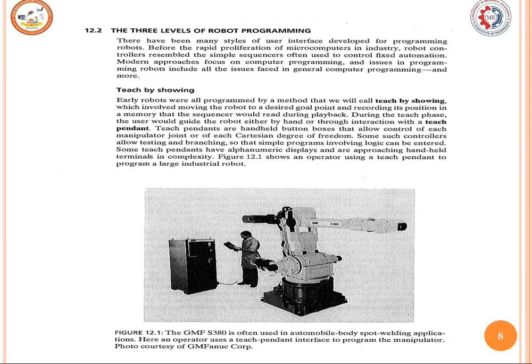So there are three levels of programming language. One is teach by show. There will be a teach pendant where, by showing the different locations, the start and the end point, if we keep on recording, and at last we play back, it is going to show the required output.